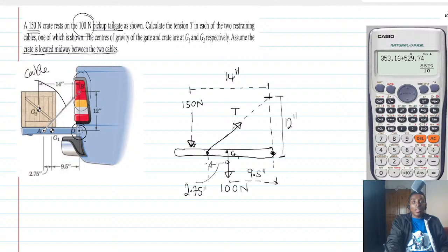Okay. So looking at O, we can clearly see that this is a hinge. Okay, a hinge. So this is O. For a hinge, I am going to get 2 reaction supports, along the X and Y. So this is going to be OX, OY, right?